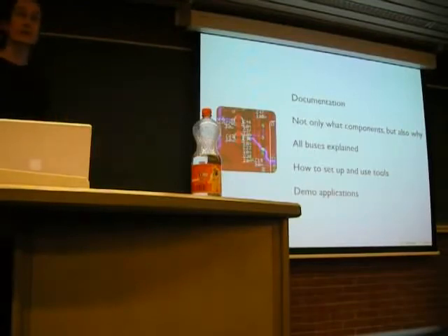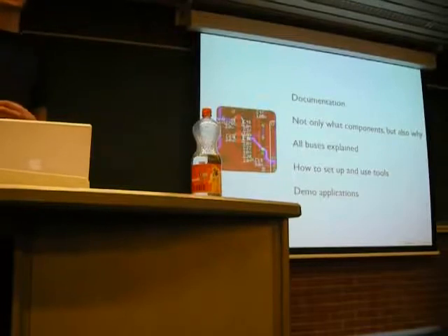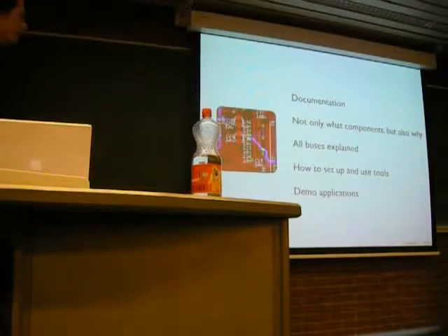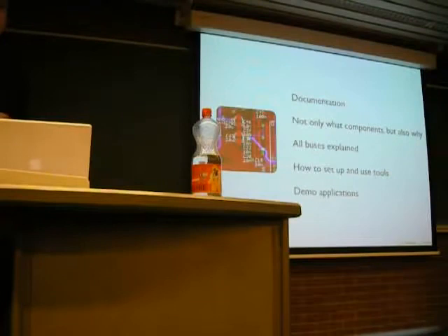USB or JTAG? Sorry? You said there are tools that let you use the JTAG bus. Yeah, there is a JTAG bus, and the USB is an FTDI chip, which really translates to a JTAG bus. Cool. And not all tools were working correctly with Xilinx chips, so I wrote a small tool to actually program through USB. Okay, using the JTAG? There's this serial engine on the FTDI chip, which I just toggled the bits on.